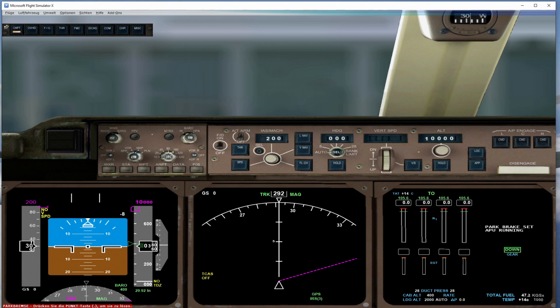Or the autopilot panel. The minimum is by default at 400 feet, put it to 0. You use hectopascals here in Germany because we're parked in Frankfurt. So switch over to hectopascals. I personally like to use the flight path vector, FPV, which gives you basically an idea how the airplane is actually moving, not only the pitch, goes up, goes down, which is as well tracked to the left or to the right. Well, ADF is not very common anymore, so many airplanes still have them, but we're not using them.